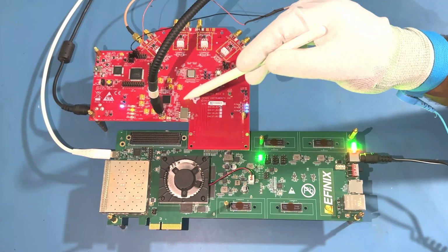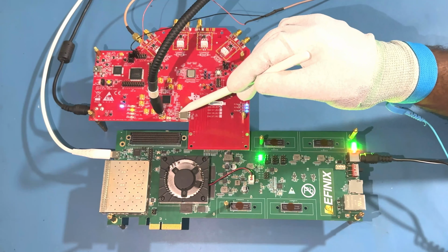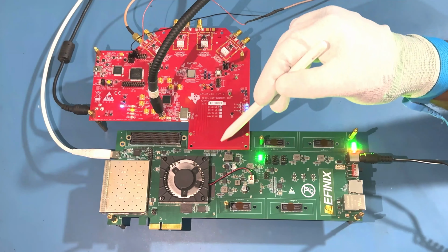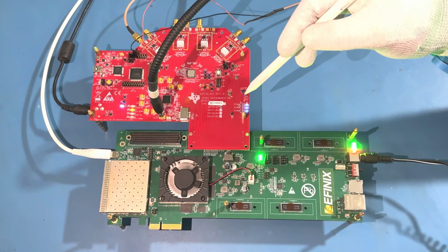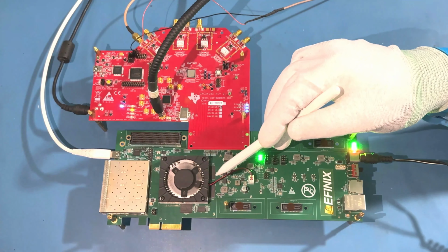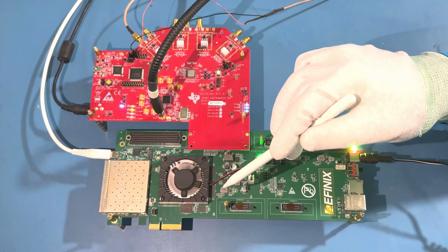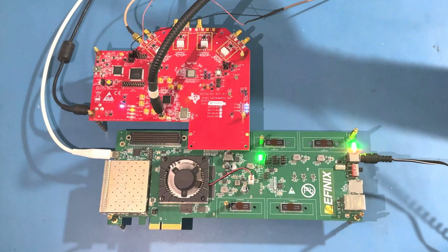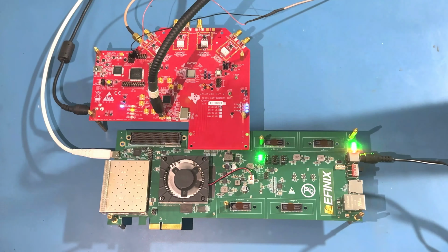For the clock source, we are using a 100 MHz external input to the LMK so that we can get jitter-free FPGA clocks, DAC clocks and sysref. The bit file, which contains the Logic Fruit JESD204B IP core, is programmed through JTAG, which is connected to the host PC.